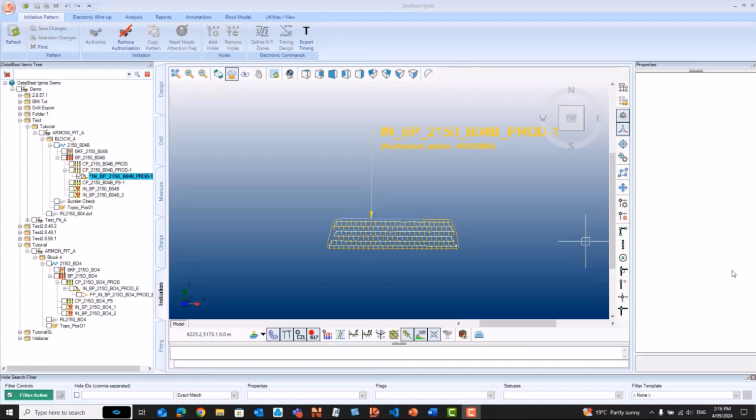1.4 to 1.8 is a very controlled blast. You have coarser fragmentation, reduced volume of broken rock in collar zone, reduced heave and muck pile mound, and no fly rock. Whereas 1.8 to 2.4 is a minimal surface activity blast, so small surface disturbance or insignificant surface effects. So basically, as you go higher with scale depth of burial, you generate less surface activity, less air blast, less noise, less heave. So it's just a measure of the amount of explosive energy centered around your particular drill holes.